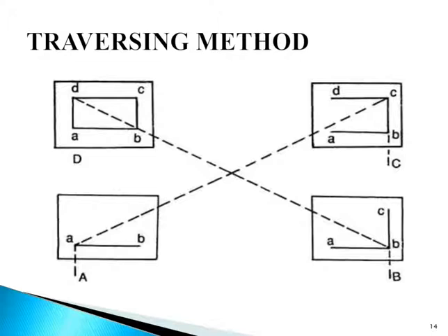So the table is then centered, leveled and clamped, and the north line is marked on the right hand top corner of the sheet. Next, with the LED touching point small a, the ranging rod at station B is bisected and a ray is drawn. So the distance AB is measured and plotted to any suitable scale as previous. Next, the table is shifted to point B and a ray is drawn and bisected. The distance is measured and plotted to any suitable scale.